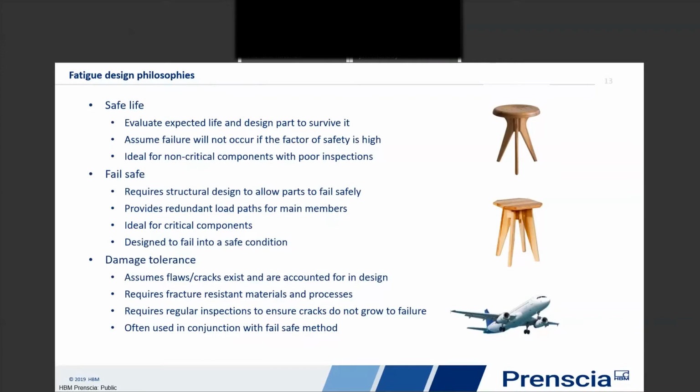And we go in, design a part with a factor of safety, hence that we try to capture the population of that part and have a life that's going to, a predicted life that will serve either the life of the part or use that predicted life to come up with a replacement schedule. But this is done looking solely at the loads, no inspections of the parts. This is easily applied to mass-produced parts of relatively low cost.